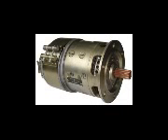Generator ratings. The generator is rated in power output. Since a generator is designed to operate at a specified voltage, the rating usually is given as the number of amperes the generator can safely supply at its rated voltage. Generator rating and performance data are stamped on the nameplate attached to the generator. When replacing a generator, it is important to choose one of the proper rating.